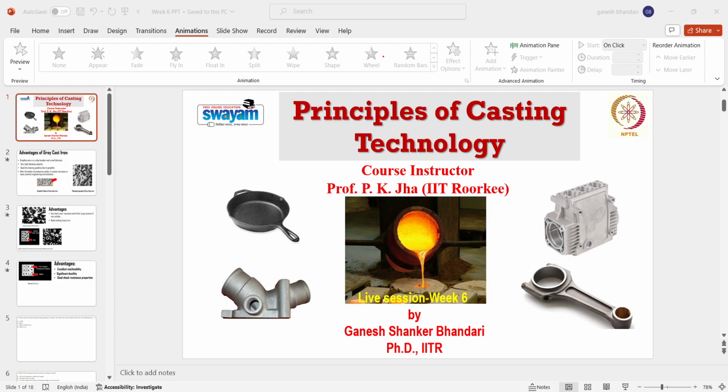And the second one is no carbonaceous material washes can be used on the mold faces. So why we use this carbonaceous material on the mold faces? To provide the fluidity to the system. When we talk about gating systems, we talk about graphite coating on those gating systems. So your material is going to have some high fluidity inside the system by avoiding the friction with the mold wall faces.